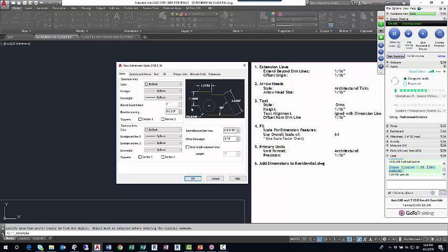That's how far the little line extends beyond the dimension line, which has the dimension value and the arrowhead and so forth. Just click the down arrow twice. That takes your 3/16 of an inch extension line down to 1/16 basically.